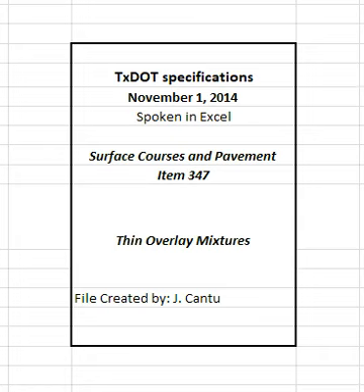Process to balance production, delivery, paving, and compaction to achieve continuous placement operations and good ride quality. Paver operations, for example operation of wings, height of mixture in auger chamber, to avoid physical and thermal segregation and other surface irregularities, and procedures to construct quality longitudinal and transverse joints. 4.4 Mixture design.